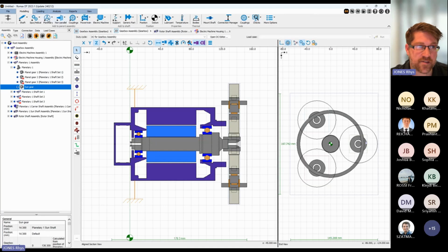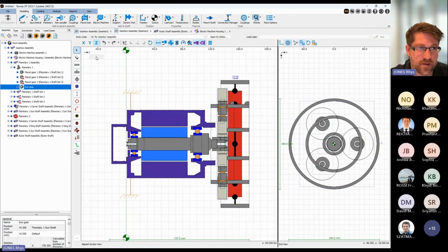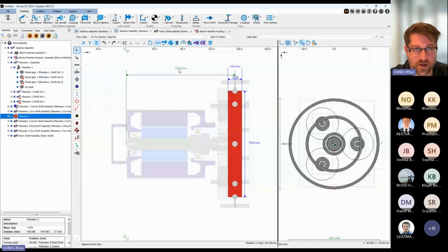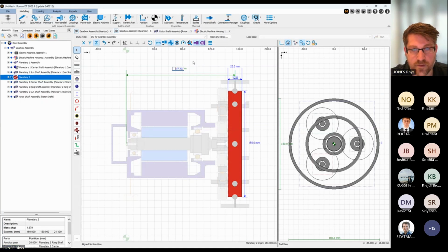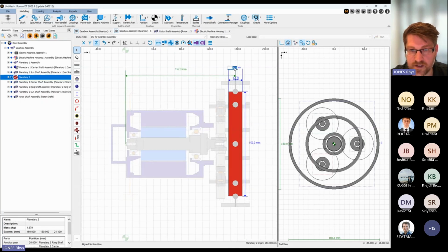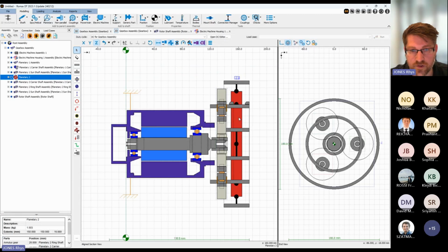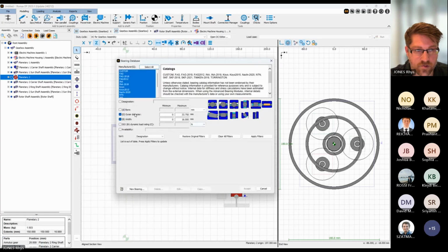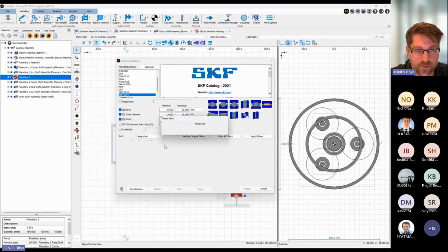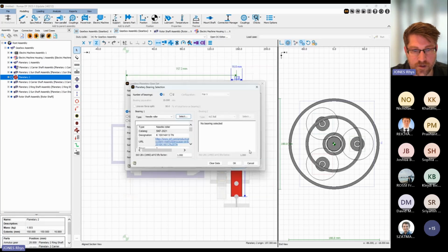We're going to create the second stage now. So we're going to do exactly the same process. I'm going to select, click on there. It's going to create my full system. Exit there. I'm going to update my position, 157.3. Update, and I'm going to make this 16 millimeters. I'm going to add the same planetary bearing on this side. Go. Apply filter. We're going to add that.